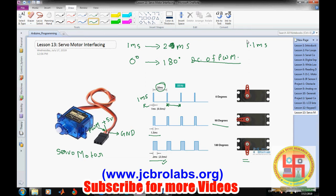It will rotate by nearly 18 degree, because in 1 millisecond duration it is taking 180 steps. So 1.1 millisecond will take 18 degree. Similarly, if you have any requirement like 37.5 degree or 40 degree or 50 degree, you can compute the pulse duration accordingly.